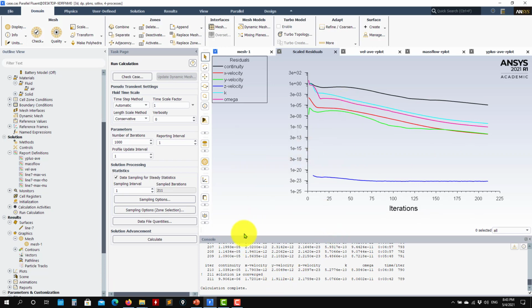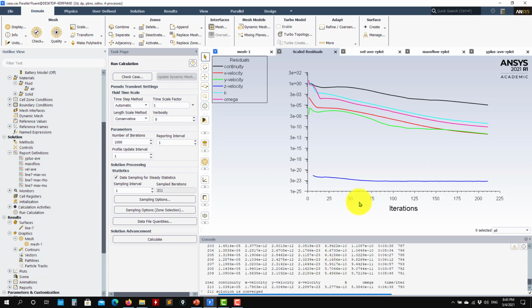So see that in this case, now this is a nice validation case because also you can push your solver to reach low residual. So these are very low residuals. Usually 10 to the minus 4 is a good industrial value, but here we're going to 10 to the minus 5 to reach a very good convergence rate. See that this one here is very low. See that it's almost machine precision.